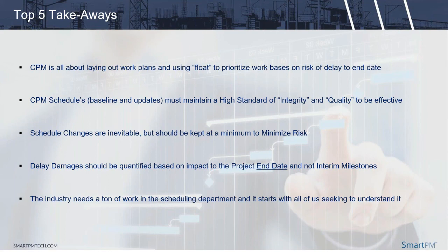The other thing that I see a lot of is people don't understand truly what delay analysis is about. It's about the impact to the end date, and the only way to understand it is understanding the longest path or the critical path driving that end date and all the activities on it at different points in time, and quantifying it. And then finally, the industry is moving in a very good direction.